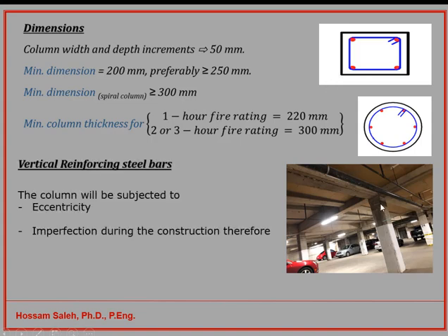Now, when you look at this concrete column, can you expect reinforced concrete inside or only concrete? So when we have this beam supported on the two columns, it can provide its reaction to this column, and another beam here provides the reaction to this column. So based on the span of the beams and the amount of force it can bring to the column, you can expect some eccentricity in the column, which means that the load will not apply at the cross section of the column. So we call that eccentricity.